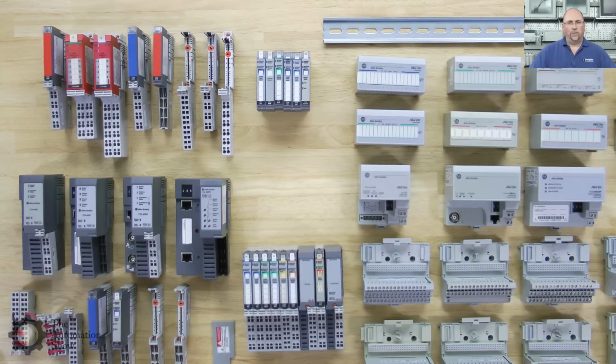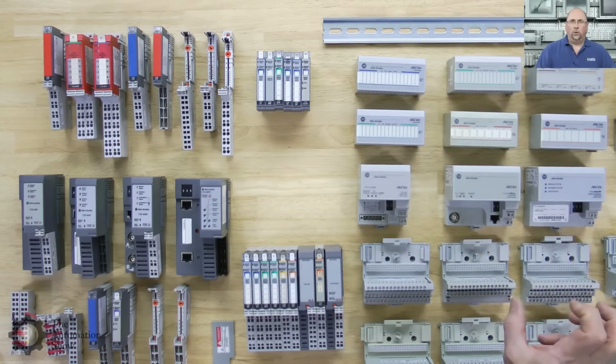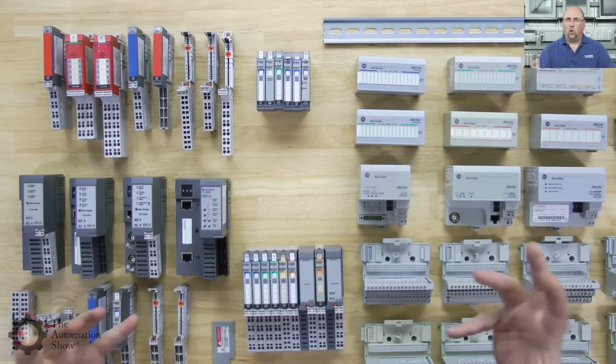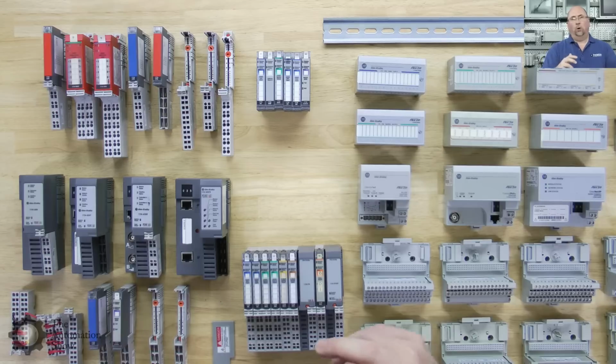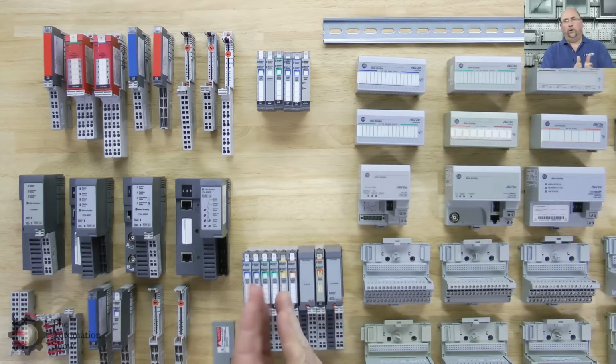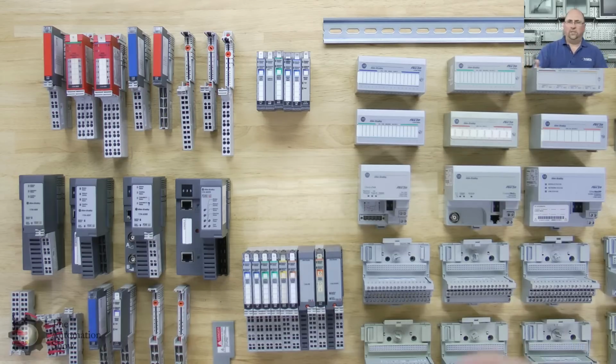So with that said, let's go ahead and get started and talk about the similarities between PointIO and FlexIO. And we'll start by looking at the fact that they're both distributed I/O lines. There's no controller that Rockwell makes that will control up to 30 local FlexIO modules or PointIO modules, right? Like we have the Compact Logics where you can have 30 or 31, 1769 or 5069 modules locally if you get the bigger processors. But that's not the case with FlexIO and PointIO.